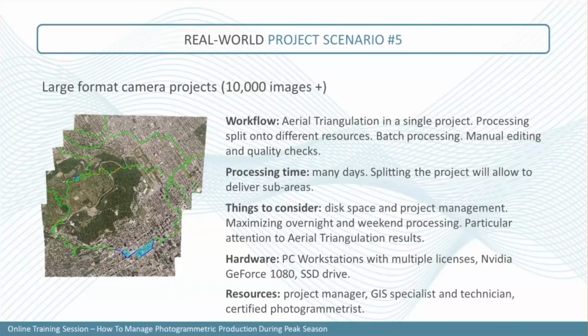What's also really important here is to carefully look at the aerial triangulation report, which is going to be the main step. As soon as you have a good aerial triangulation, if your ground control points residuals are fairly low and you're sure that you have a good AT, then you can jump to the next module. But since you're managing large data sets, it's really important to do some QC at every step. It's really important to do some good QC.